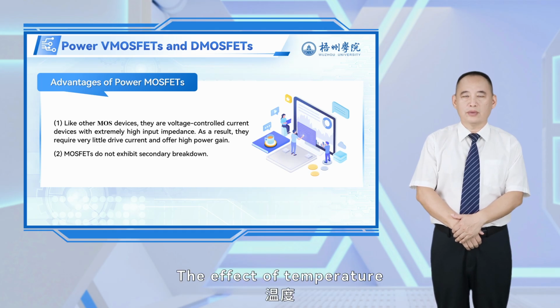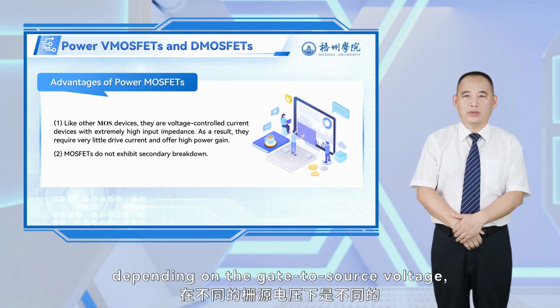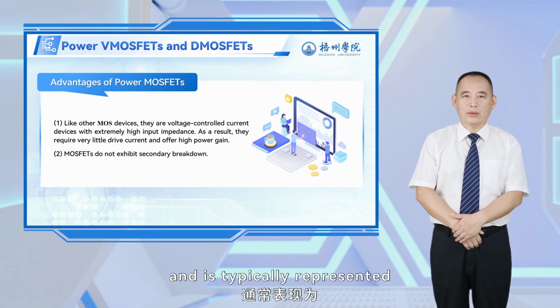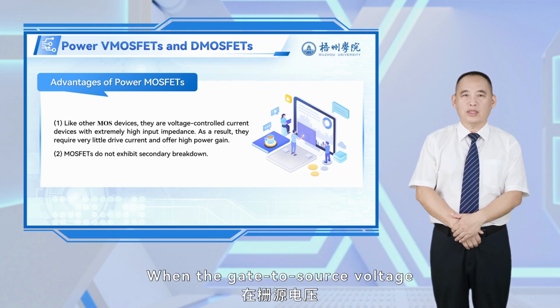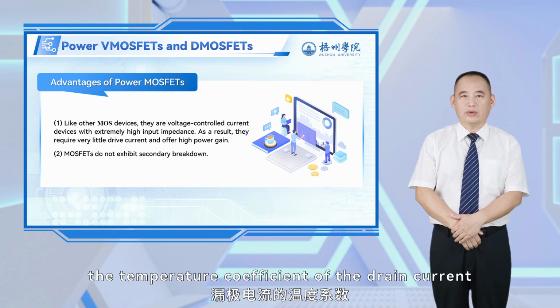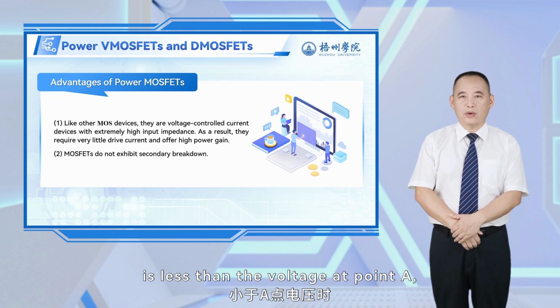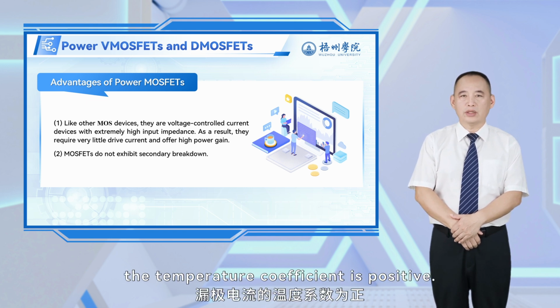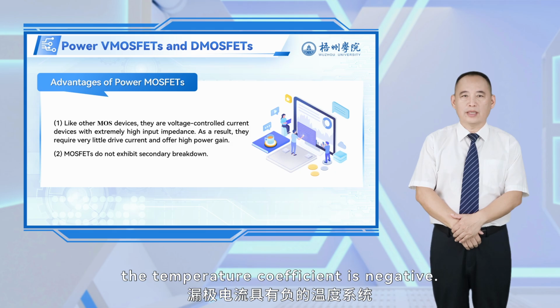The effect of temperature on the drain current of a MOSFET varies depending on the gate-to-source voltage, and is typically represented in the form shown in the graph. When the gate-to-source voltage equals the voltage at point A, the temperature coefficient of the drain current is 0. When the gate-to-source voltage is less than the voltage at point A, the temperature coefficient is positive. When it is greater than the voltage at point A, the temperature coefficient is negative.